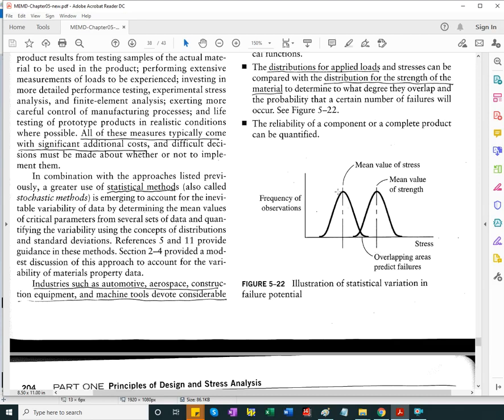As for loading, of course, limiting the overloads. There are ways of doing this. Any dampeners, if any, or other types of load monitoring are going to limit the probability of failure. But again, we can work on the material, and we can train the people that use the product, say it's a vehicle or an airplane, and reduce the probability of failure.